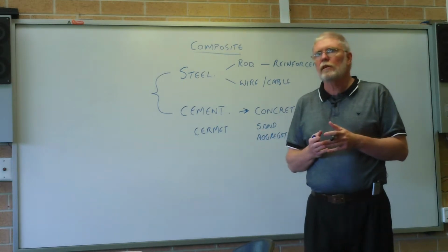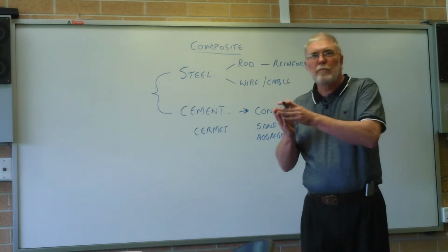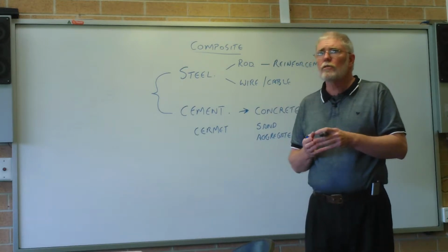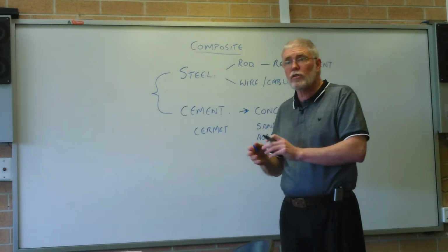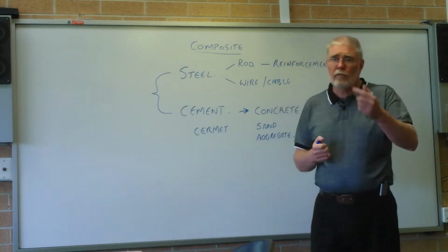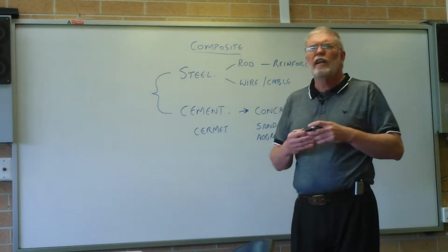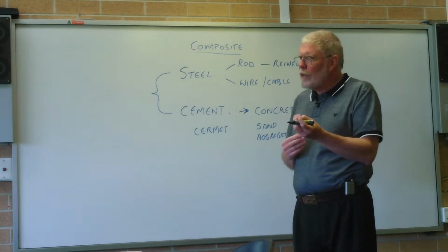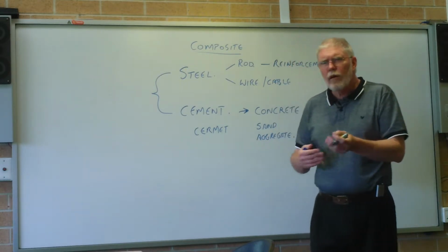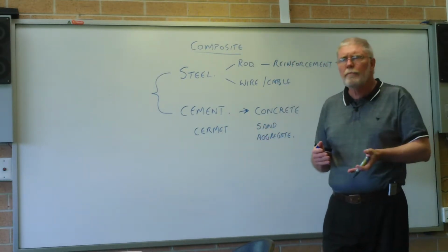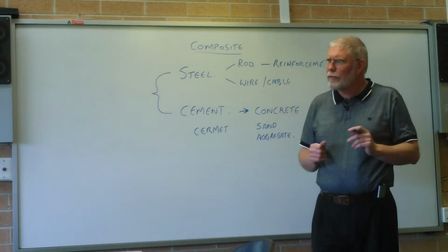Most cement mixes are going to have more than 50, maybe 60% of the mixture made up of the calcium oxide. The rest, the silica oxides, the aluminium oxides and the iron oxides, are there. And that's why cement has that sort of grey colour, not white. Limestone, think of the cliffs of Dover. Yeah, big cliffs, white cliffs of Dover.